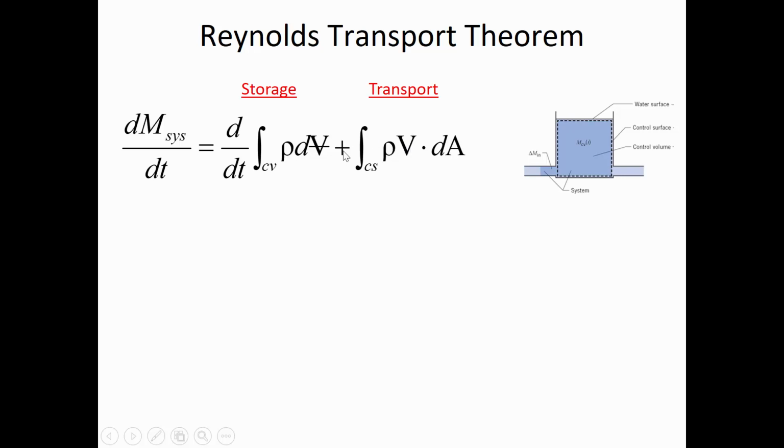So velocity and volume. In the case of the storage term, if we multiply the volume by density, then that's how we're getting some system mass. Remember that the continuity relationship can be expressed in terms of volumetric flow rates or mass flow rates. Now mass is always conserved. Volume usually is, but not always.